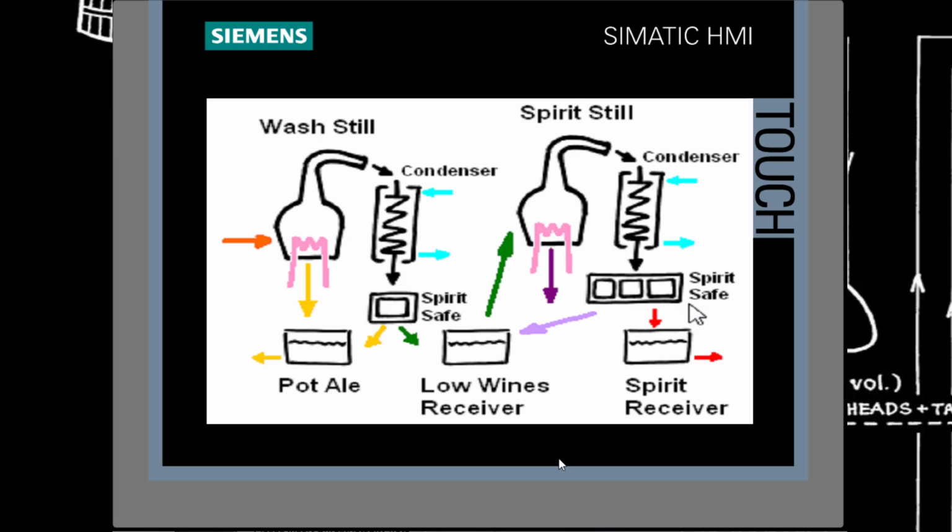The first cut varies from manufacturer to manufacturer, but it's normally around the 70% mark for whiskey, and then we carry on measuring down until we get to our final cut for the production that goes into the spirit receiver, which can be about 60 to 65%. That's called the heart. That's what we want to use.